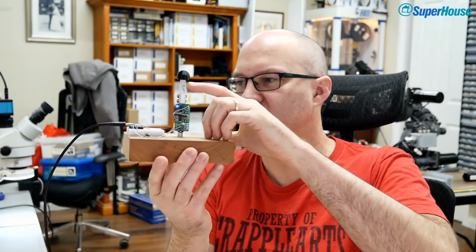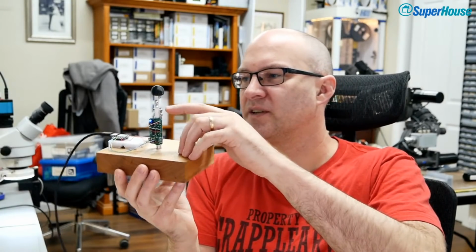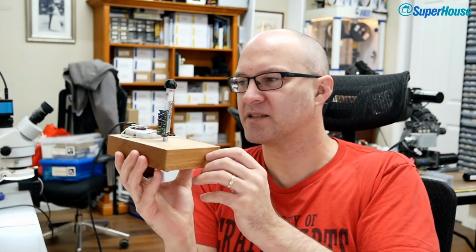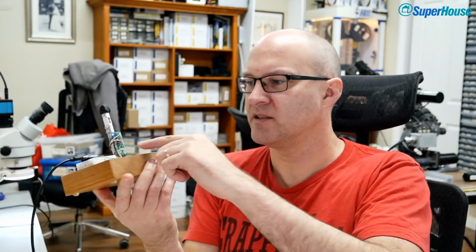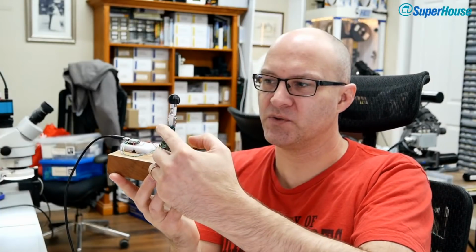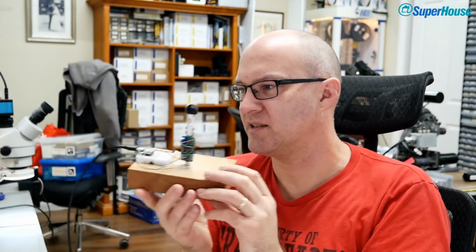So there is a load cell that you can see here. It's the same sort of thing as you would find in kitchen scales. And there's one load cell for the x-axis and one for the y-axis, so they're set at 90 degrees apart. This little circuit board on the side is a board I designed that's got dual amplifiers on it. No, not amplifiers. They're 24-bit analog to digital converters. So these are running as a Wheatstone bridge sort of arrangement going into the ADCs, and then that's being read. So we can measure the force that's applied in x and y axes.